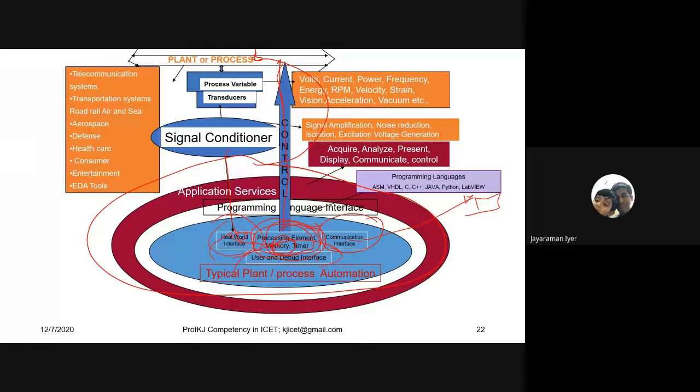Next, in the unlikely event of a deviation: a deviation should not come, but it will come, due to the environment, and we will talk about the environment slightly later. There is likely to be a deviation, and the deviation has to be brought under control. That is what it is supposed to do. In the unlikely event of a deviation, the embedded controller generates a counteracting signal applied to the plant to bring the deviated variable or variables back to their normal operating condition.